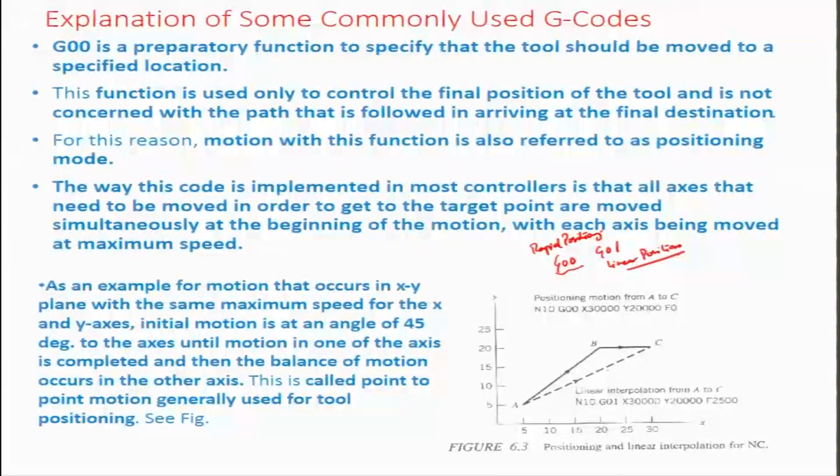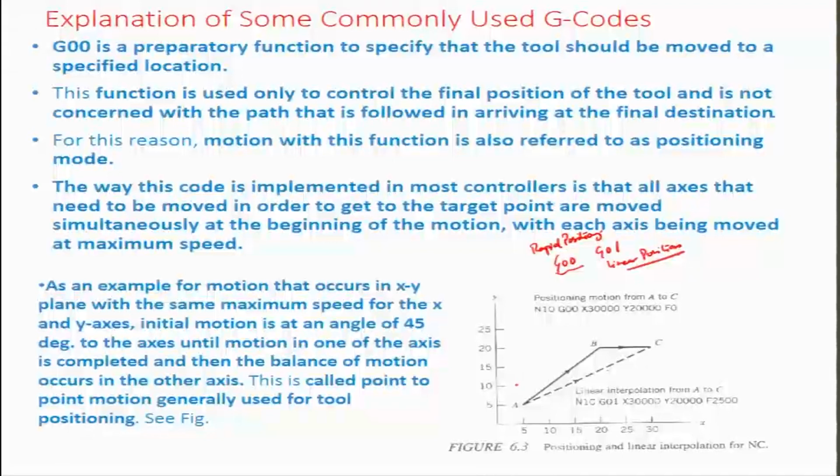which would be in accordance with the material properties, tool properties, the failure criteria, all these different issues associated with such tooling. So the rapid positioning is about a path which is represented here very well by the solid line. Let us say in a certain operation, you would like to go from position A to the point C. So, there are two ways of doing it. One is of course a direct translation from A to C through the dotted line, and another is going from A to B and then from B to C. The question that is asked normally is which of these paths is more in terms of time and which may be lesser in terms of time, and so it is really about utilizing controller capabilities.